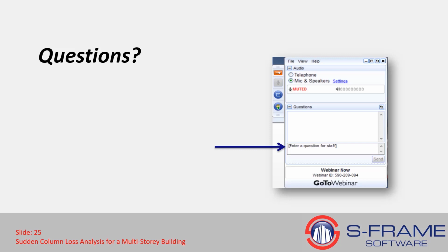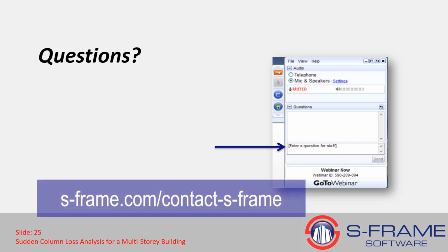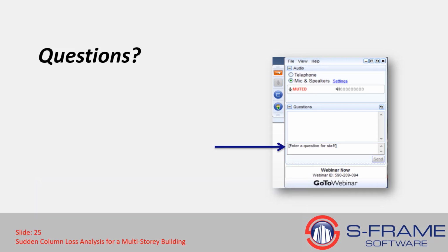I have time for one more question, and this one is related to the damping coefficients we calculated. For those values, we actually use a spreadsheet that is available to you upon request. So you can enter your damping coefficients and natural frequencies, and from there you can calculate the alpha and beta values automatically. You can also use the formulas that are referenced in the document and in this presentation to calculate those values.